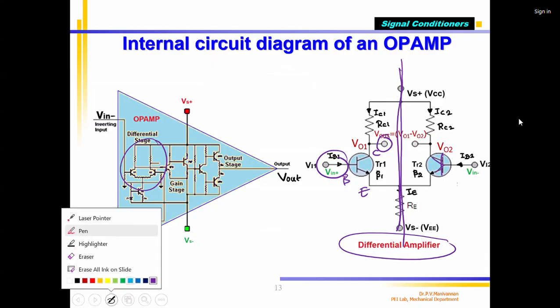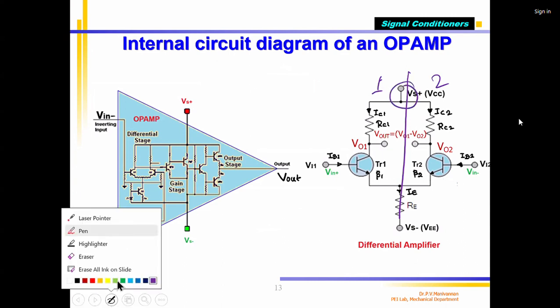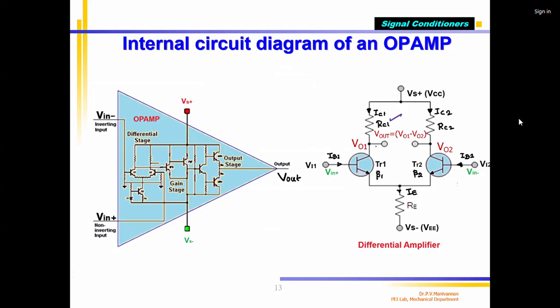Similarly, on the right side also, you have base and emitter, this is one more common emitter stage. Now what I do, I connect both emitters together, with a common VCC. But note down the important thing: RC is separate, collector here and here also separate. Correct? Base I am giving separate voltage here also, so different base currents IB can flow depending on how I connect. This is my RB with a power supply, and similarly another RB with a power supply, this is VBB. The VBB is what we call V1, V2.